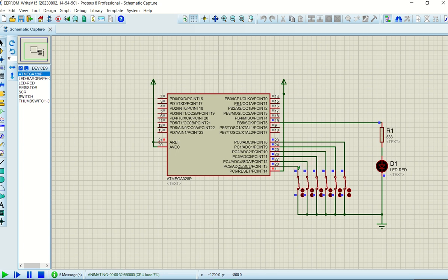So if I make this a 1, that is the 2. That's where I get the 10. This is where the 2 comes from. And on these 4 lower bits, if I make this one a 1, you'll see now I'm sitting at a value of 2, 8 hex, and that's where the LED switches on. Any other combination, let me just open this one here, it will switch off, because now I'm sitting with a value of 2, 9 hex, which is not 2, 8, and the LED is off, so they are not the same. Whenever it's 28 hex, it will definitely switch on the LED, because the comparison shows the two are exactly the same.